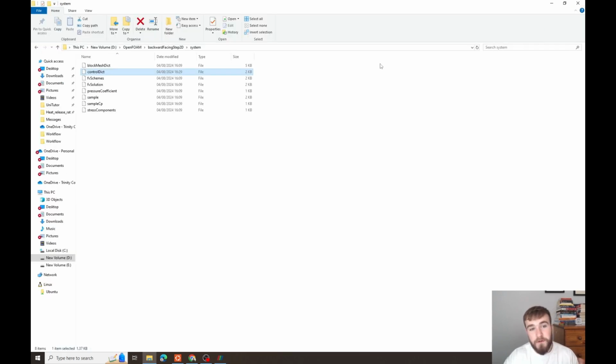So there's all the files that you need to define an OpenFOAM simulation. It will be different from solver to solver. So if you're using the PISO algorithm, it'll be a little bit different. The PIMPLE algorithm, it'll be a little bit different. And also maybe if you're using a different solver for heat transfer or combustion, you would also need some extra files at the boundary like temperature, mass fractions and stuff like that. But enough blabbing, I'm just going to run the simulation now.